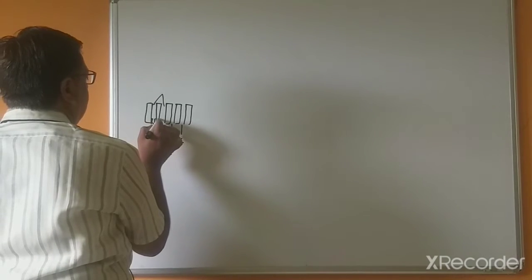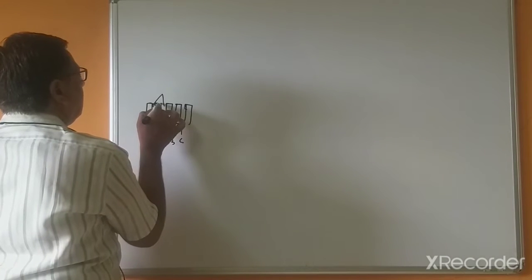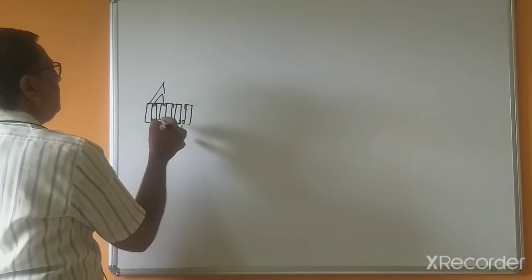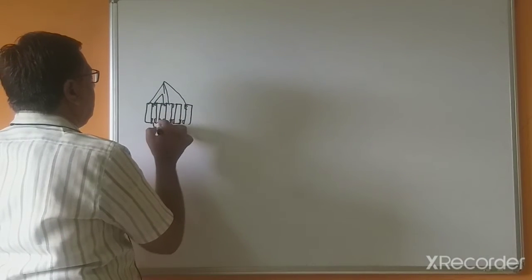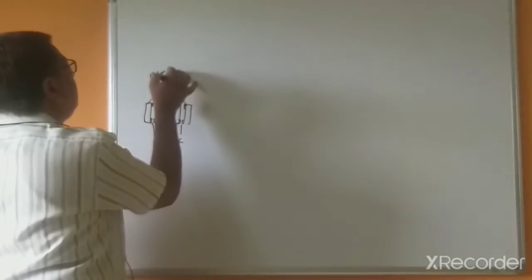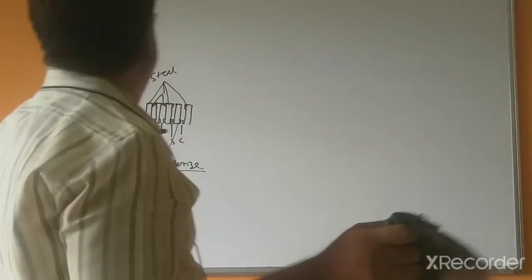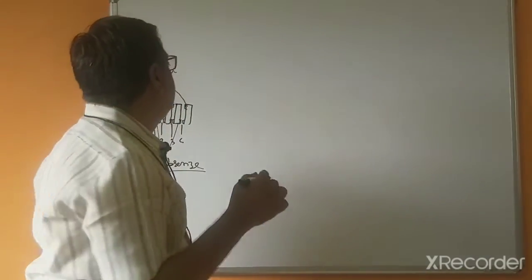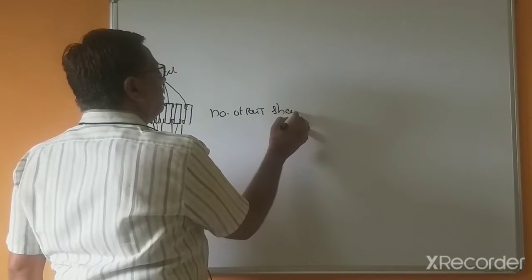So here the friction material is on both sides. This outside material is steel, and this material is bronze. So these are 3 steel plates and 2 bronze plates, because this is steel and this is bronze, which is a popular material for clutches. For a multi-plate clutch, always remember the number of plates or number of pairs should be even.